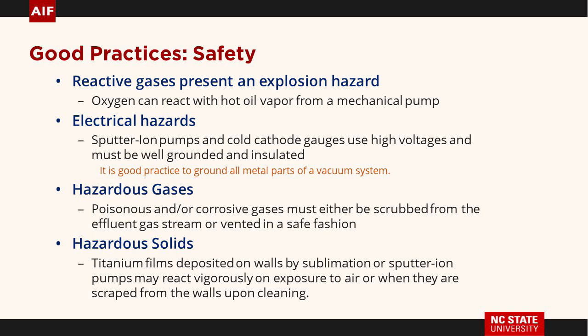And I know if you're doing CVD or something like that, you may be working with some very nasty gases. We'll talk about that and about ways that people handle them. These sputter ion pumps and cold cathode gauges have high voltages on them all the time. May not kill you, but you won't like it. So you have to remember that high voltages may be present. Hazardous gases, that's where you have to have some way to vent them or have a scrubber or something like that to contain them. Hazardous solids, those titanium films, are very reactive. So if you just open a system, you may have a problem if you touch it.